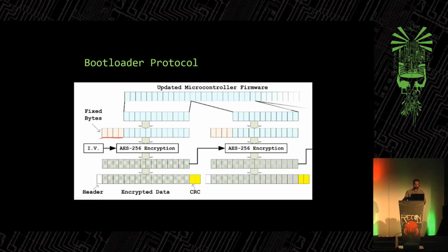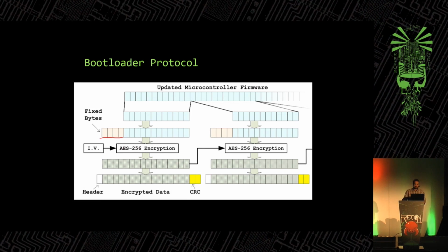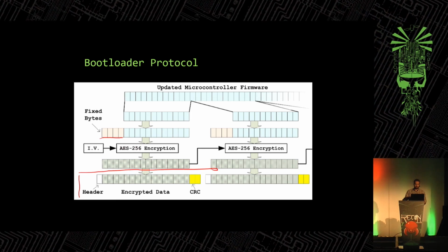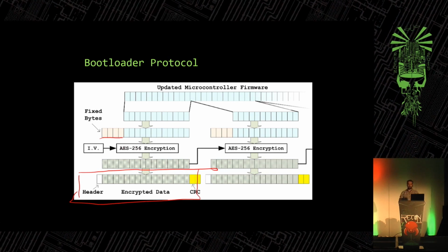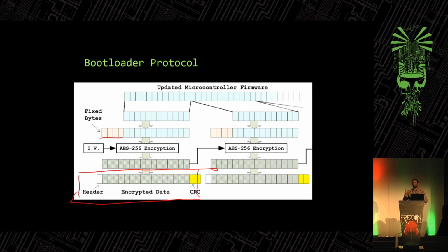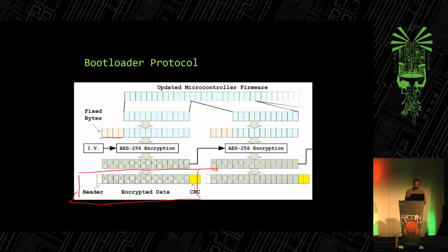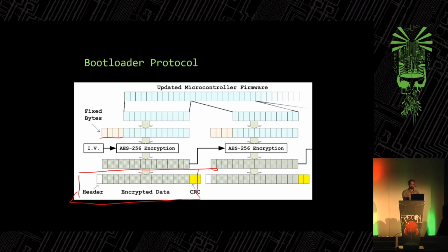So what's interesting to us, and it's used in a CBC mode, is that if we just send the device a block like this, of encrypted data, we put the CRC on it, we put the header on it, it's going to decrypt it and check the signature. The signature will fail and it'll throw it away. But again, we don't care about that. We care that we were able to get the device to decrypt it properly.